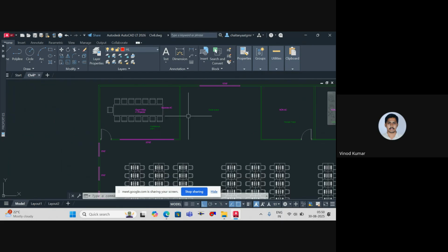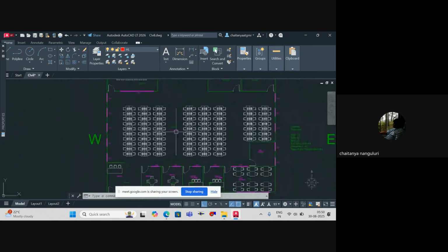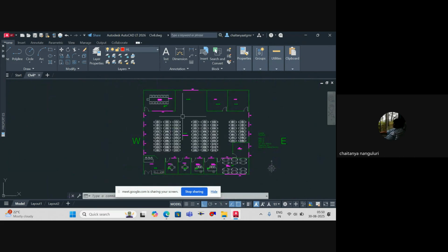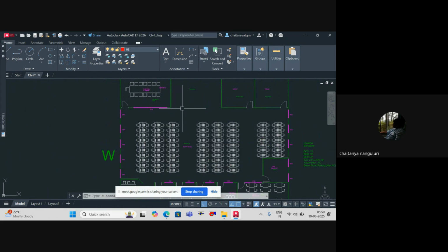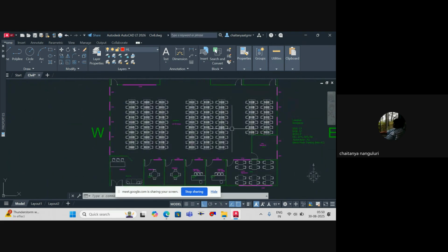Okay. So what we'll do is this completely around 30 tons we got. We will try, because the highest available VRF system is 8 TR. Or else we can even go for DX system. That means we can customize the AHU and separately connect our DX unit. So for the workstation we'll do it separately, and we'll do VRF system only for these areas. Is it fine?